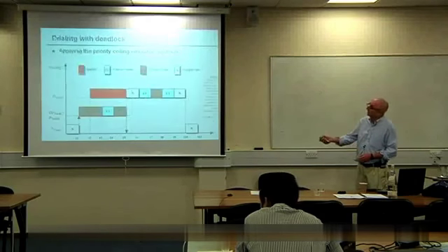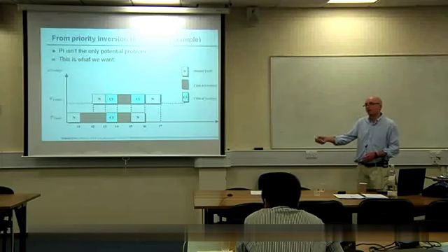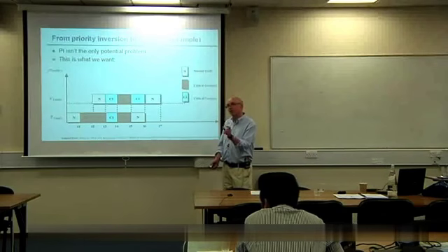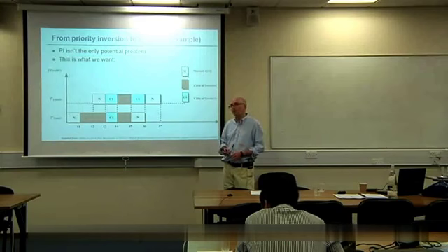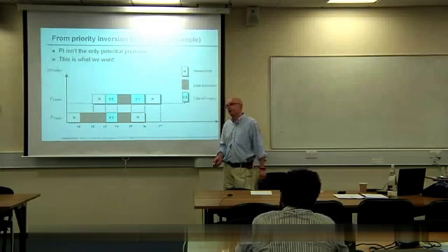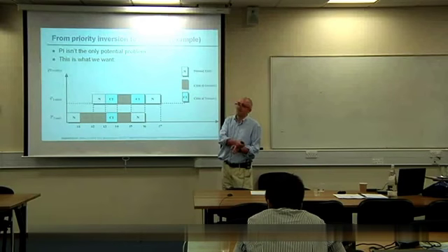Let me take you back a chunk, because some of you are still looking skeptical here. The world rarely works like this. What I've done here is I've said, these are nice little chunks of critical sections, and they're exactly one time period long. In reality, that's probably 35 microseconds long this time. Next time it runs, it's probably 45. And next time, maybe 13.5.